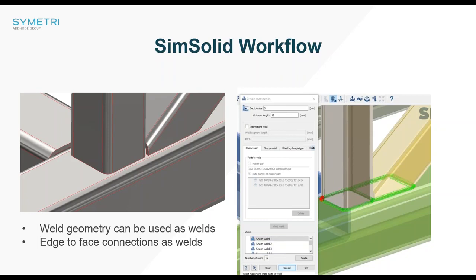So basically what happens is SimSolid, in this example which we did on a frame 2 weeks ago, will create edge to face contacts. So this box section here, you can see it will create an edge contact to simulate the weld. Now it is not simulating the actual weld size, it is simply calculating or contacting the edge of this box section all the way around onto the face of the frame, and that's how it works.